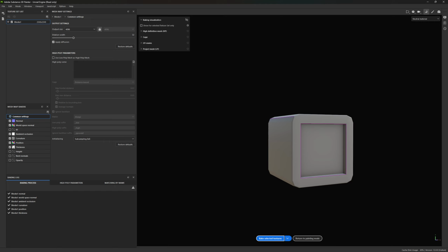Now, then you have add soft ambient occlusion, which is our next one, right? This map here adds a soft light in crevices, important for realism, right? So as you can see here, if I hover over it, I get a little bit of shadows, probably right around here from where the UVs are set up. You can see the little dark areas there.